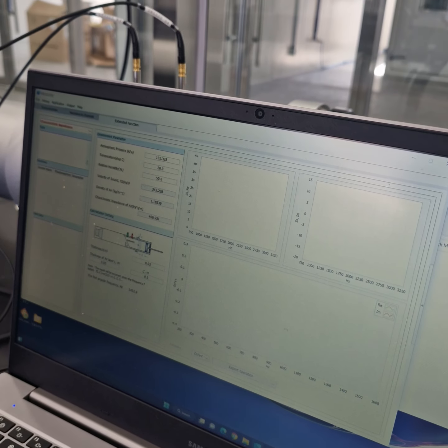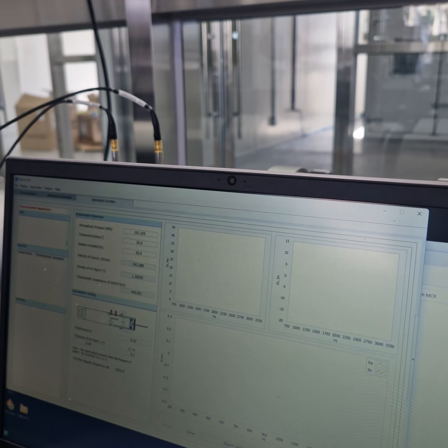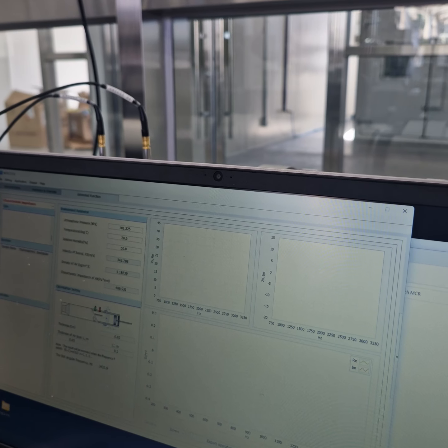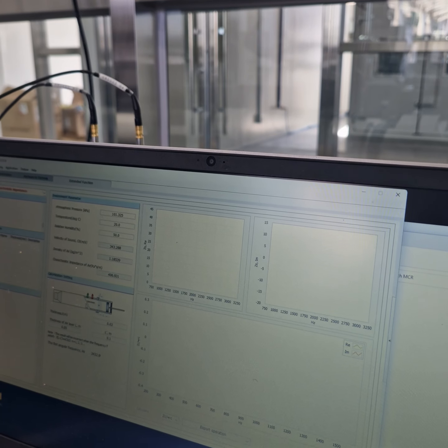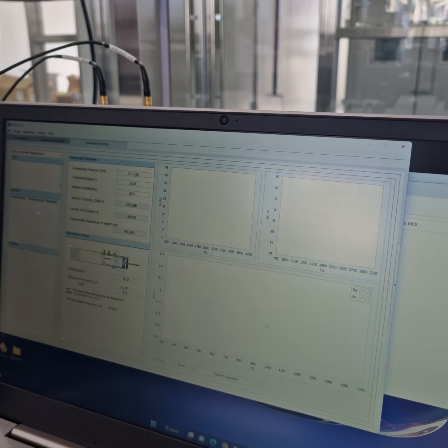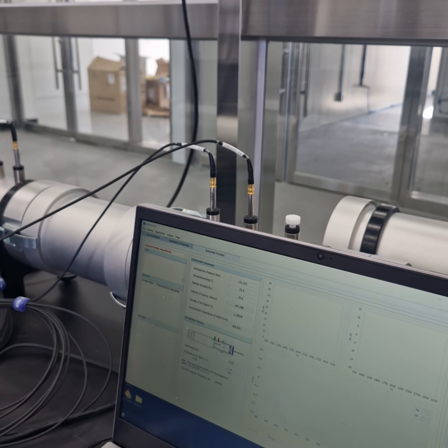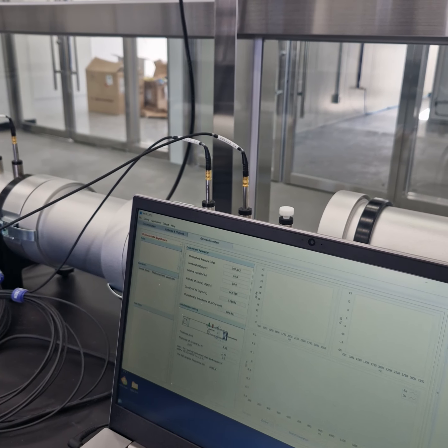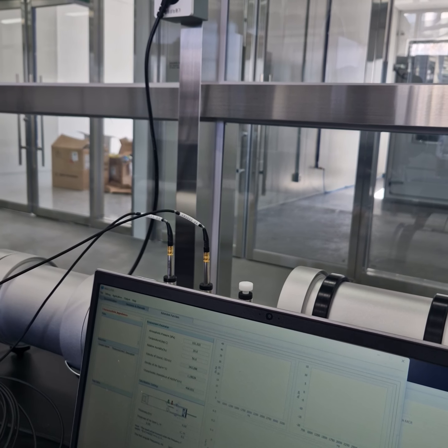These two greatly determine the acoustic property of the material. To get them, one way is to use the four microphone setup for the transmission loss test, and this test will give you all the parameters that you need.